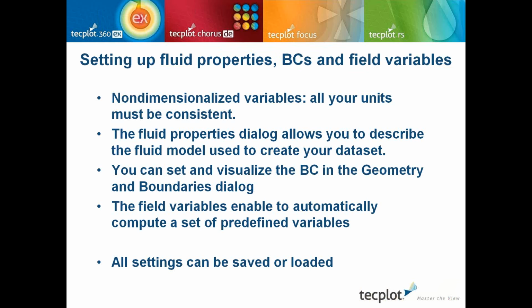First of all, how to set up fluid properties, boundary conditions, and field variables within Tecplot. The essential thing you should know is that Tecplot works without dimensions, so all of your units must be consistent. Namely, if you're expressing your length in meters and your time in seconds, your velocity should be in meters per second, or your volume in cubic meters.